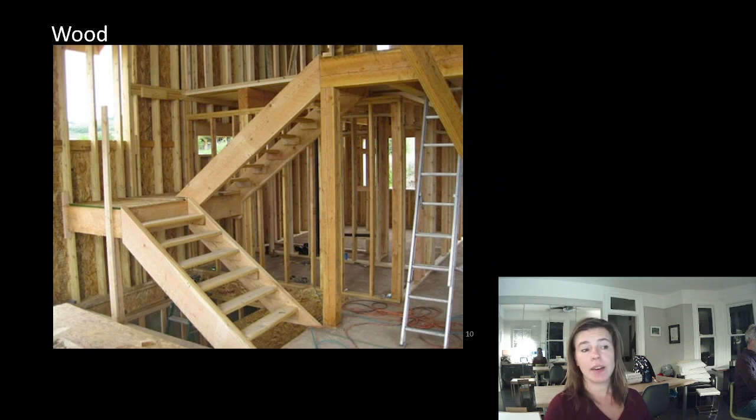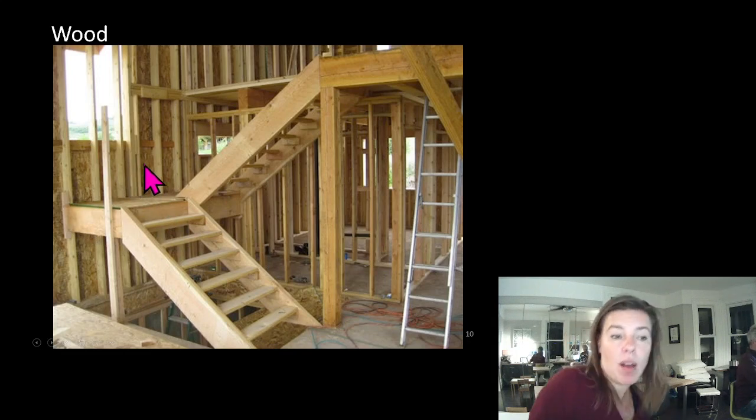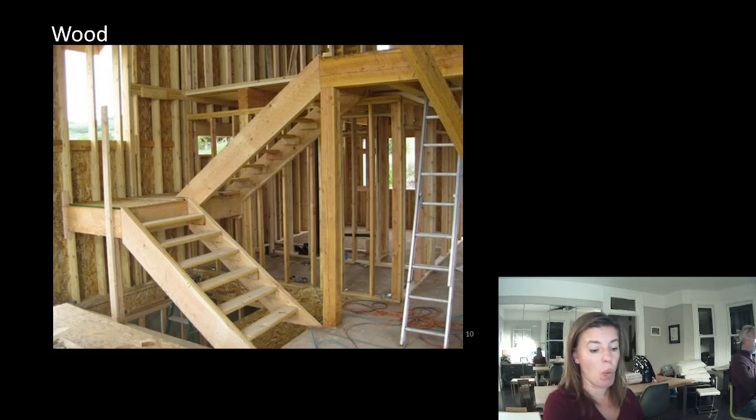So we can have wood stairs. Here you have very standard construction. And see we've got a mid-height landing. This one's been connected to the building here. So we've got 3 points of support. We've got the upper floor, we've got the landing attached to the wall, and we've got the floor here. Sometimes these are not actually connected to a wall. So you'll see that often in switchback stairs where there's no wall.